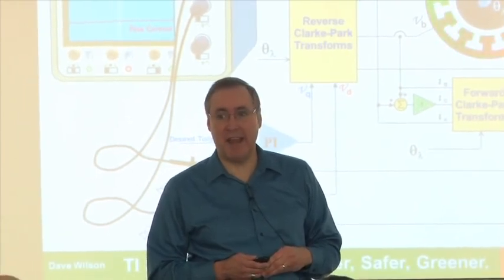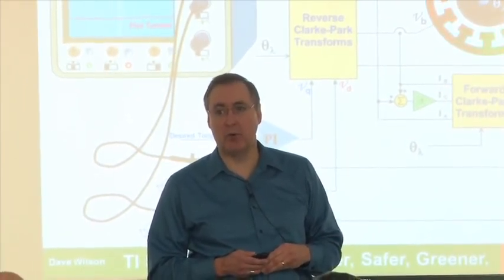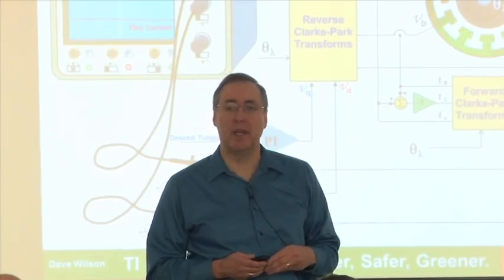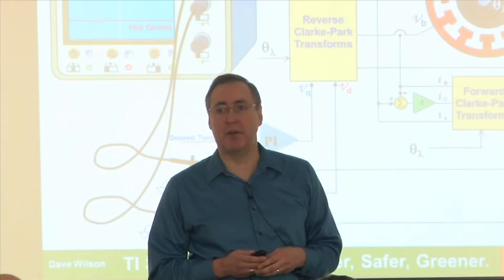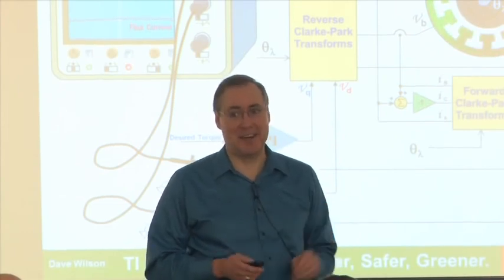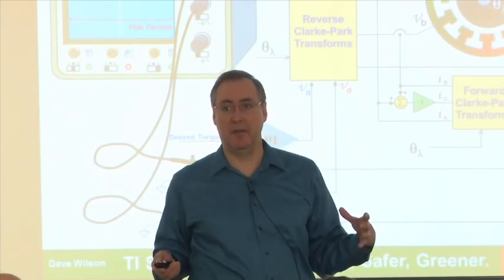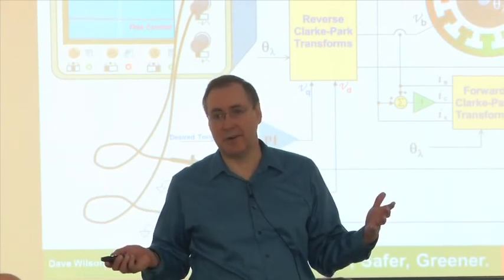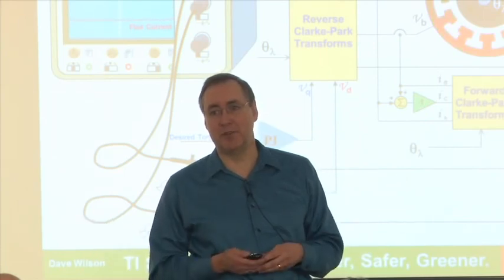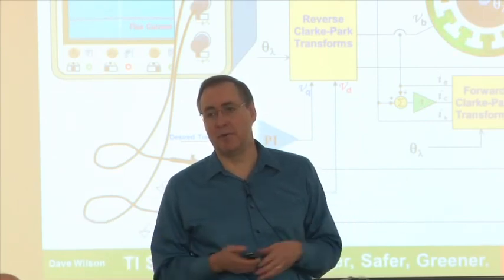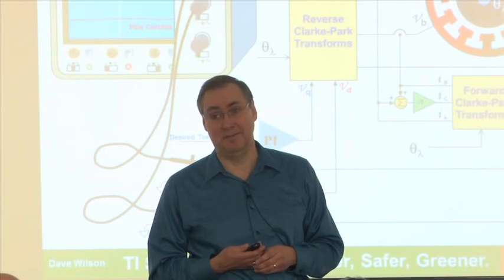Most of the time where we need that kind of resolution is when you're doing digital control, like digital power control applications where your PWM frequency is maybe 200 or 300 kilohertz. Then you need that kind of resolution. But in most cases, we've got enough iron in most motors that we can PWM at 20 kilohertz, and a resolution of just a 12-bit number or whatever, 16-bit number, is good enough.